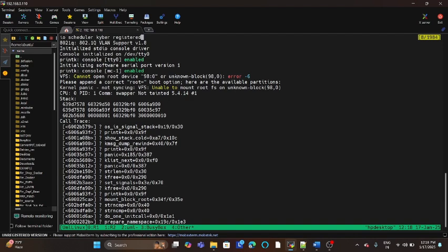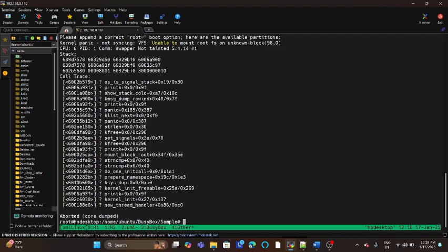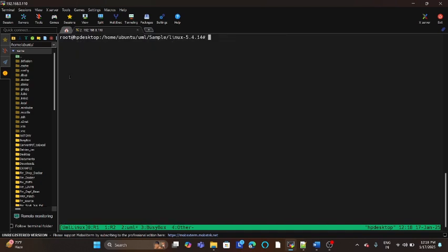Now we are saying cannot open the VFS file system. That means in the Linux kernel some virtual driver may be missing. So now we will see whether we have enabled that. Now go back to the Linux where we have compiled. Just do make menuconfig, make menuconfig ARCH equal to